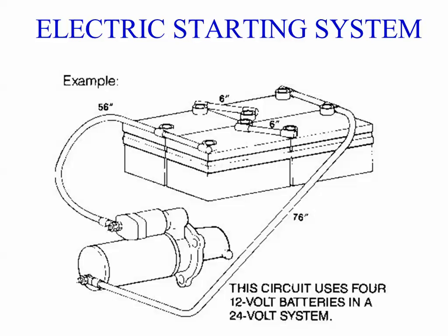And normally the way you'll do that is to get the 24 volts. In most cases, you're taking 12-volt batteries and connecting them in series and in parallel. You connect two in parallel in series to get the 24 volts, and then they may even have them in series to get in parallel to give you more amperage. So again, if you want to go from 12 to 24 volts, you put two 12-volt batteries in series, and to get more cranking amps, you put them in parallel.